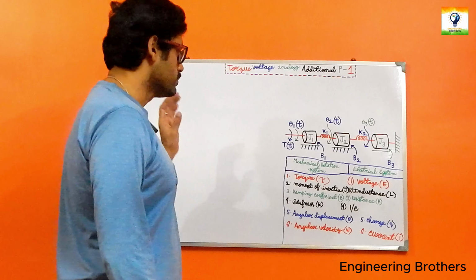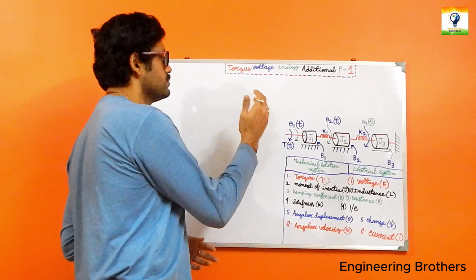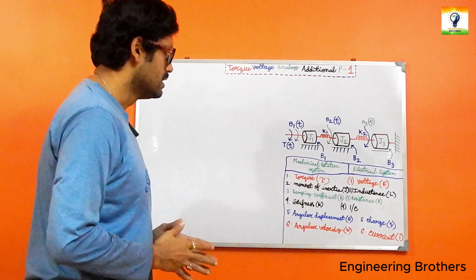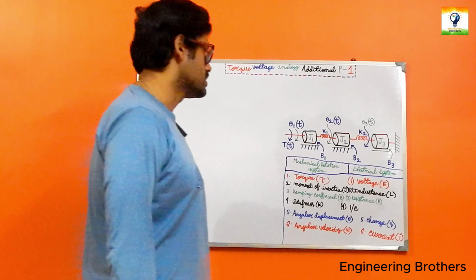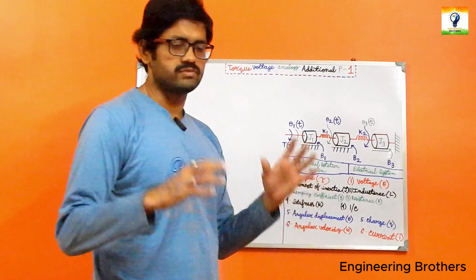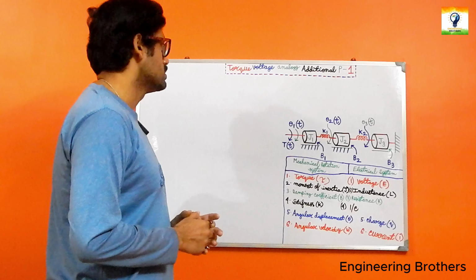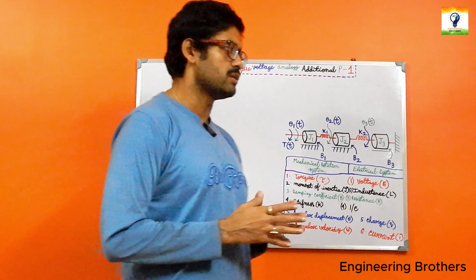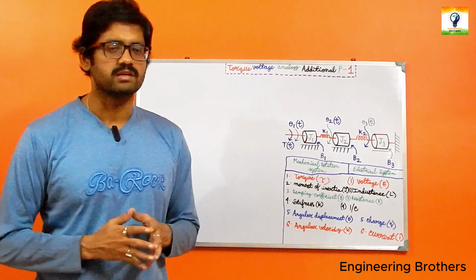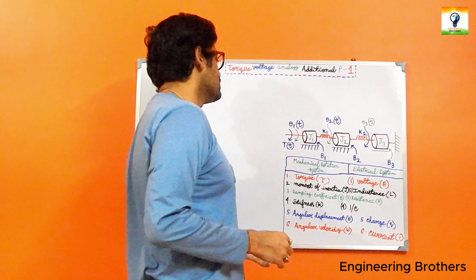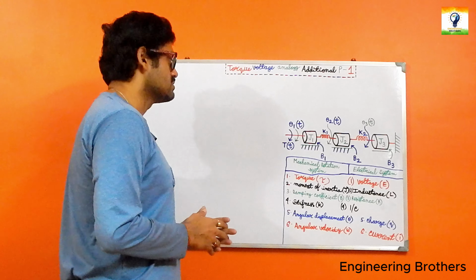And we need to find out what are the connected elements with our theta 1(t), theta 2(t), and theta 3(t). J1, J2, J3 are quite naturally our moments of inertia, and this is analogous with our force voltage analogies, and force voltage analogy concepts are applied for our translational system. In this consideration, we are just trying to consider our mechanical rotational systems.